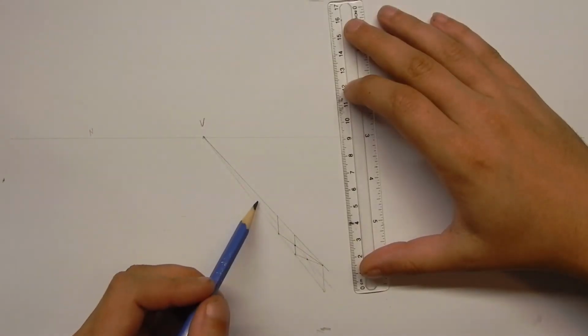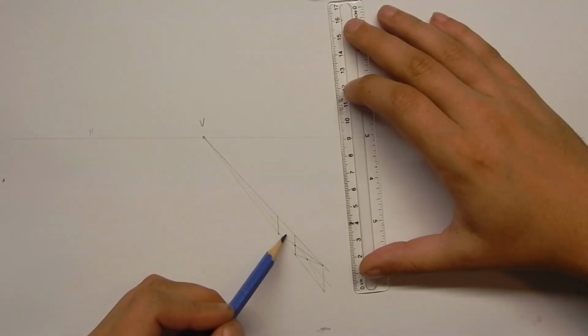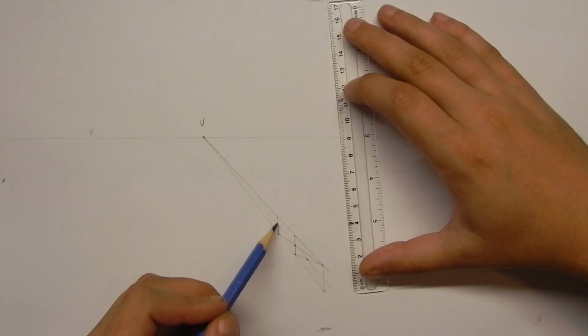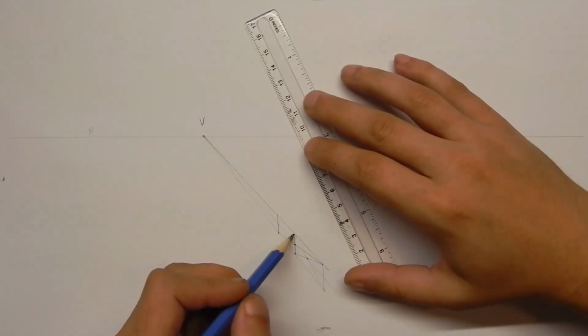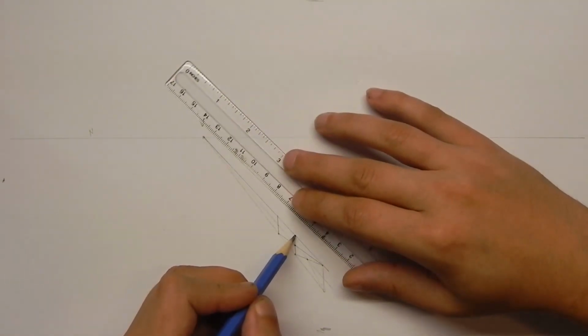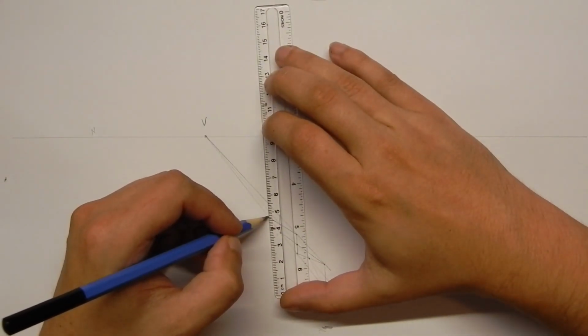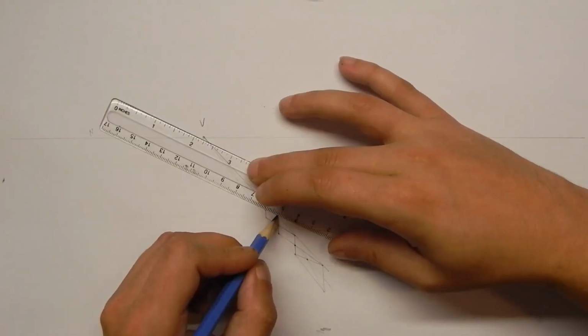Since we already have this third helper line, we don't need a corner-to-corner center point here anymore, just because our third pillar already meets the third helper line. Now we can go through yet again: second pillar, halfway through, third pillar. You can repeat this until your fence is done.